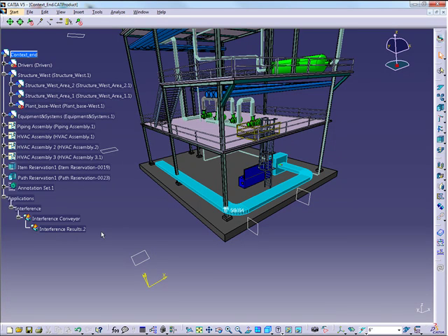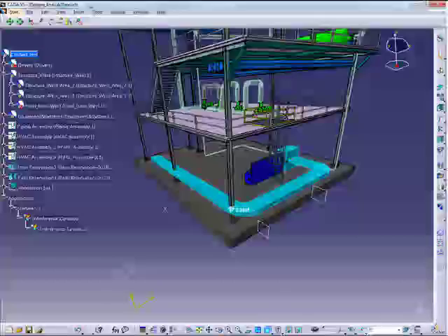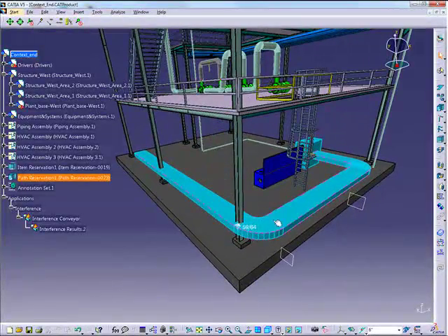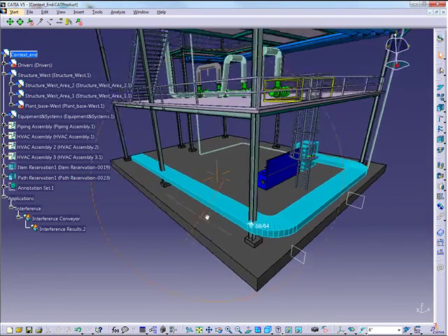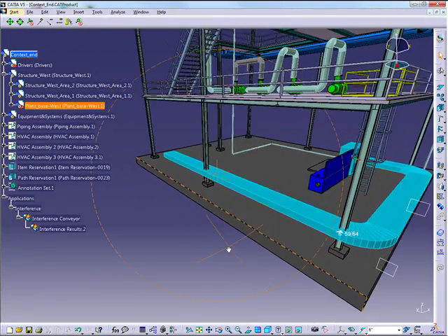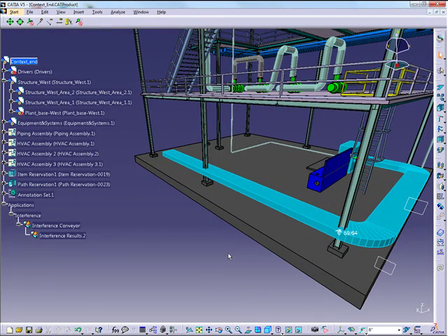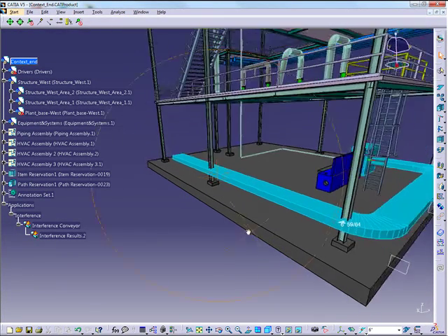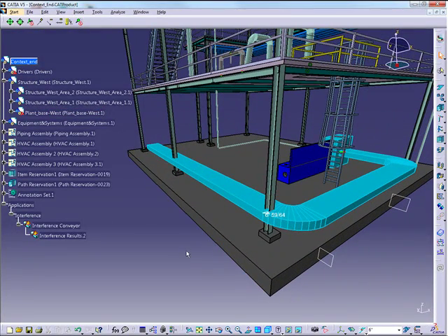So, Juan brings up a good point. At this stage, we're using the space reservation to create a coordination model. For example, the planner, the person who is designing and laying out this system, is going to be able to use this model as a strategy for coordinating with others and finding collisions. Before they commit to a more complex model, they're able to use the space planning tool to create a reservation within the building for routing their specific system, in this case a conveyor.